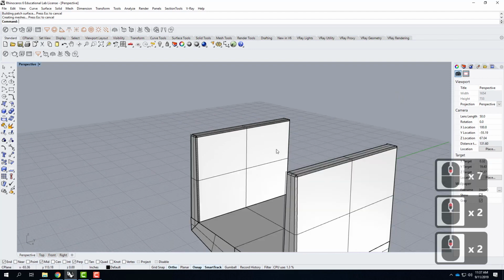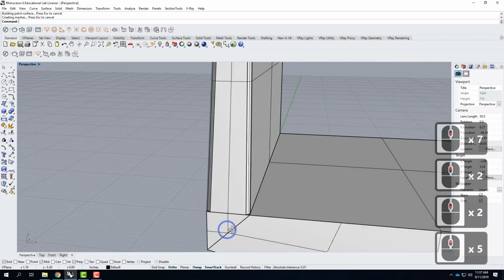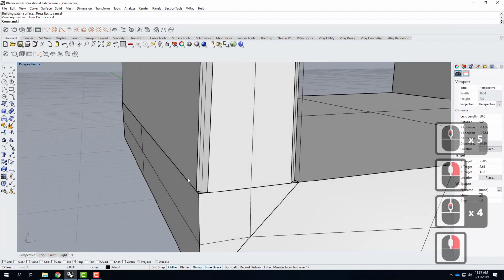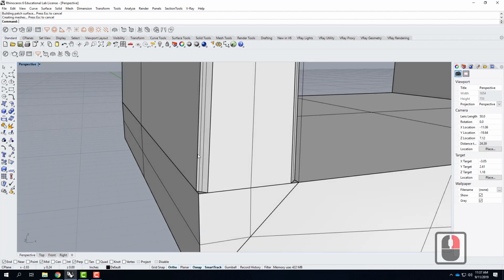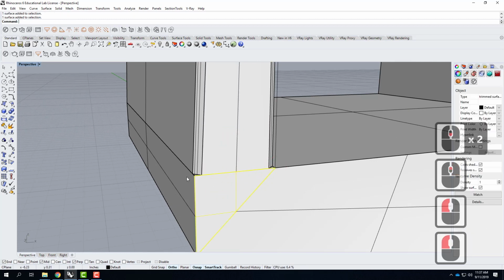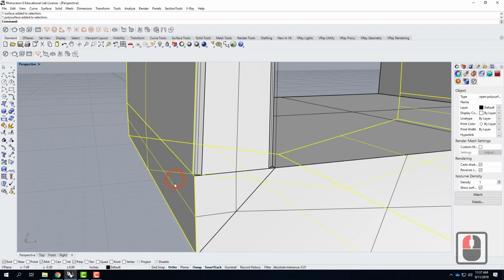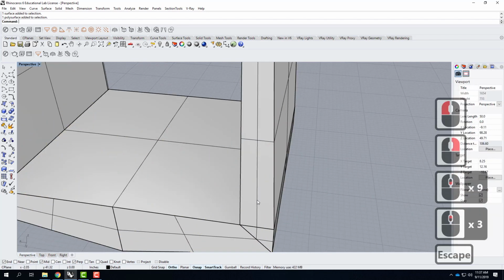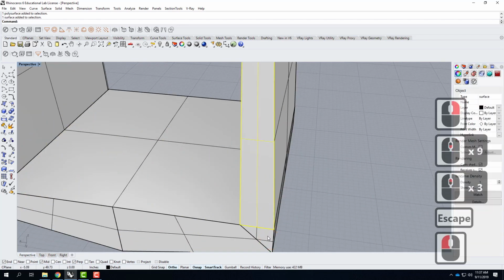So I've done this side, and I've done that side, but I haven't paid any attention to what's happening down below. So here's a good opportunity to see how I've adjusted this. When I created the surfaces on the end here, I did a separate surface right here so that when I do the chamfer, it'll chamfer to this surface here cleanly. If I did it this way, let me show you an example here.